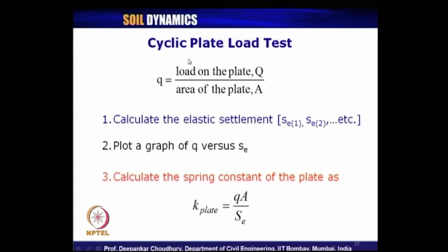So, in the cyclic plate load test, what is the procedure? Let us note it. The force per unit area acting on the plate is nothing but the total load applied on the plate, say capital Q, divided by the area of the plate.